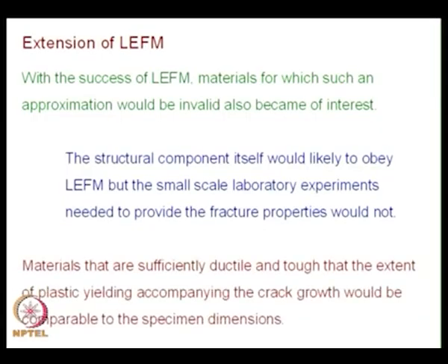People want to find out the relevant fracture parameters to characterize a particular material in service. So, this is another dimension why people were looking for newer ways of handling the plastic zone near the crack. What you will have to note is materials that are sufficiently ductile and tough that the extent of plastic yielding accompanying the crack growth would be comparable to the specimen dimensions. So, this is the goal. If you have this kind of a situation, how will you go and do it?